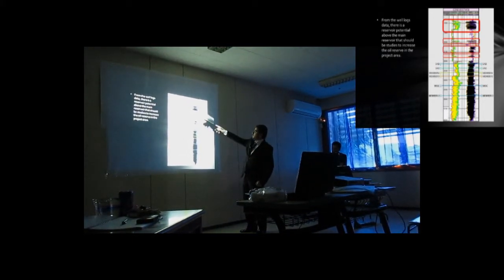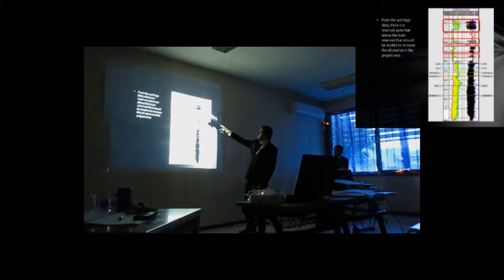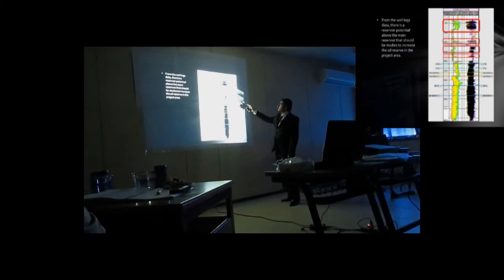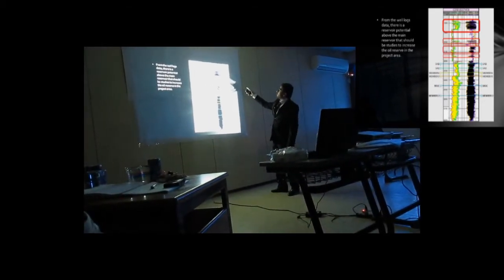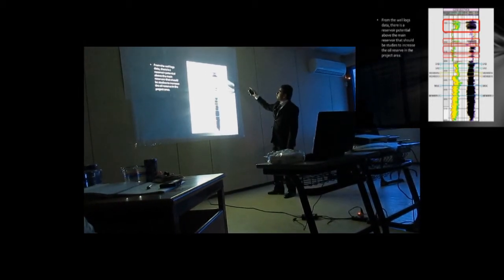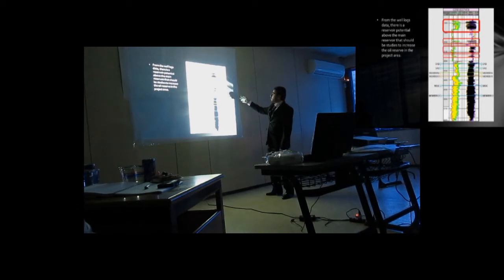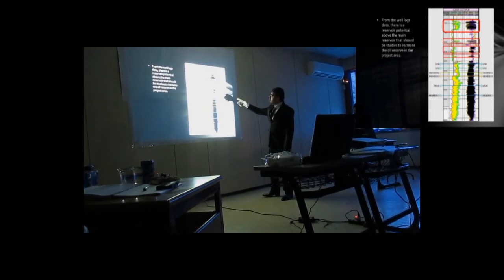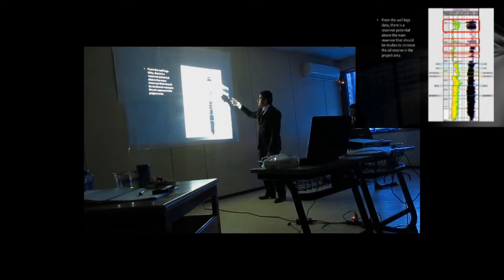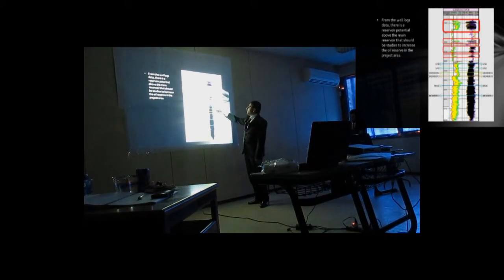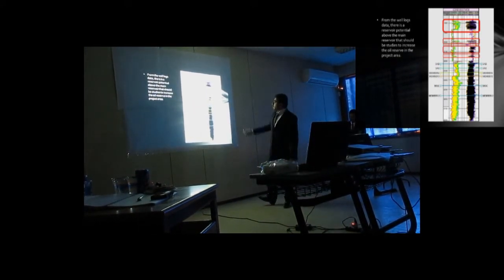As you can see, it is represented at the depth of 7,800. This is from the neutron and density logs and the crossover of the shallow and deep resistivity, showing that this area has oil. This area is above our area of study 5AB.